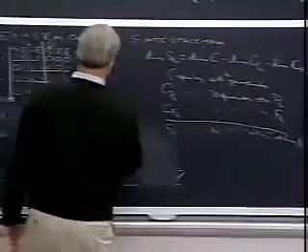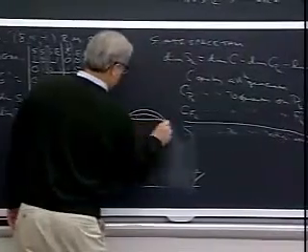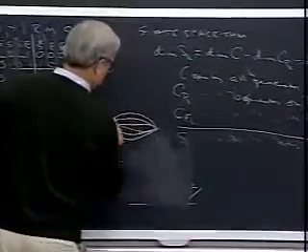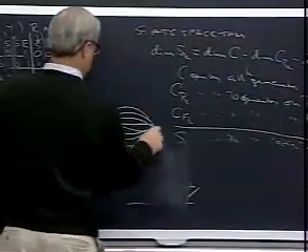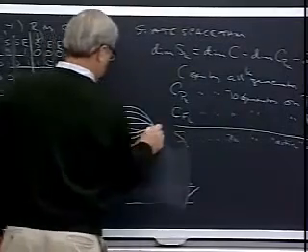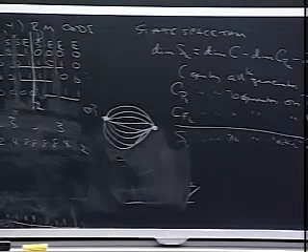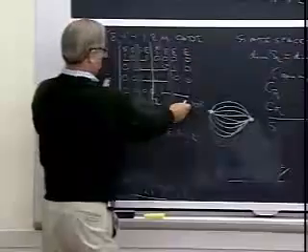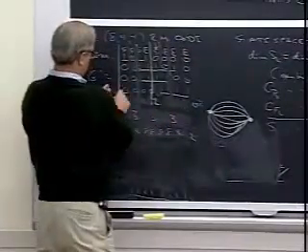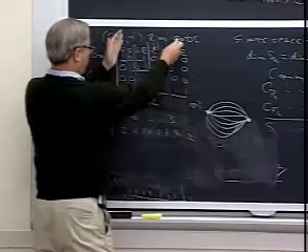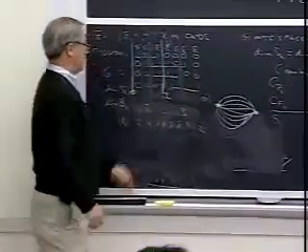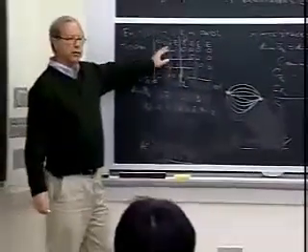What does that trellis look like? Looks like 16 parallel transitions from beginning to end. That's a legitimate trellis, right? Just have 1 state at the beginning and 1 state at the end and 16 transitions. Is that what we get if we went through this? Yeah. We have 0, 0, and what's the branch complexity? It's 4. The dimension of the branch space is 4 if we took the whole thing.